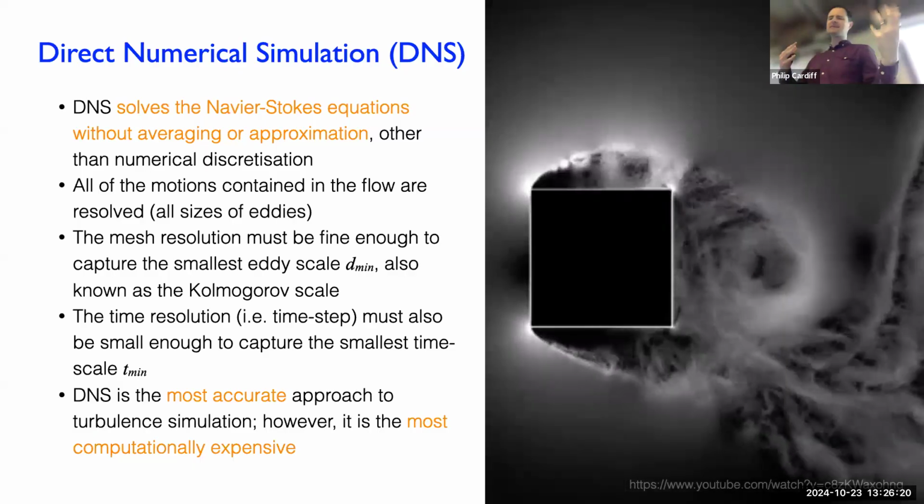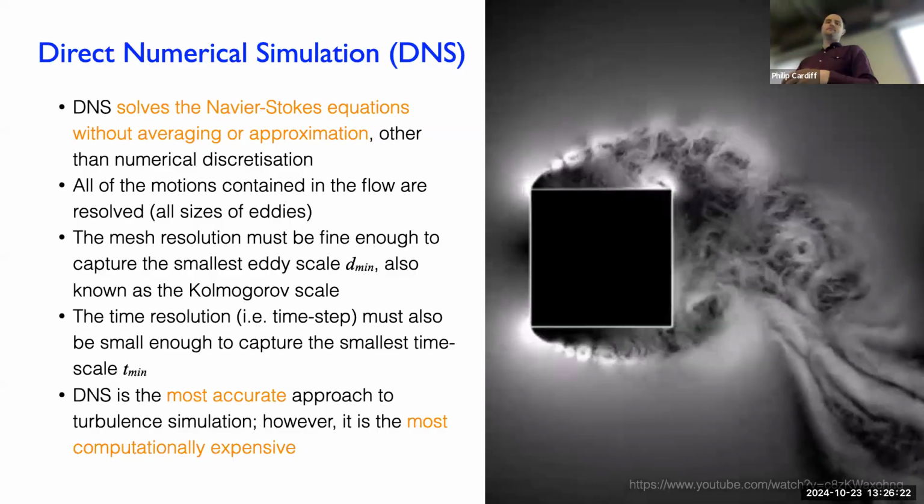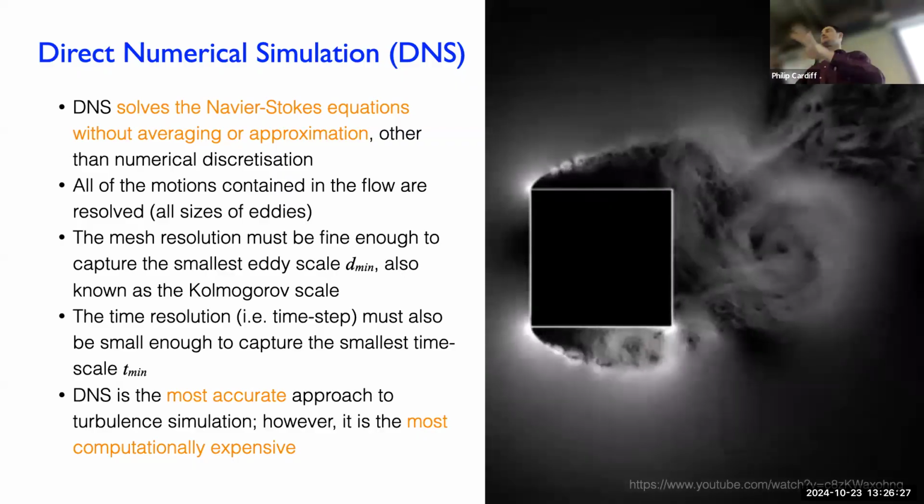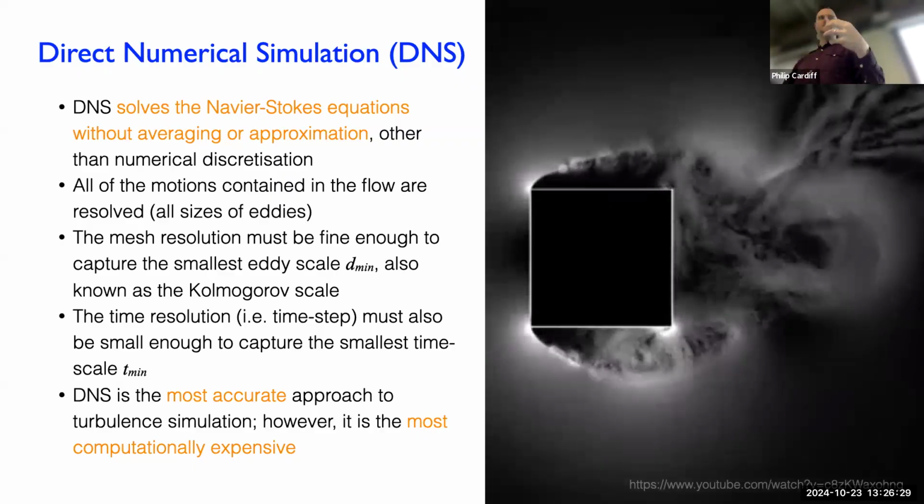Sometimes there are misleading quotes about turbulence, where people say turbulence is not mathematically understood. There are lots of things at a high level that may be difficult to predict, but the actual mathematical equations, the Navier-Stokes equations, fully describe turbulence deterministically. They're very sensitive to initial conditions. But if we calculate the Kolmogorov scales, and make our mesh fine enough and our time step fine enough, it will describe all of that. There are some practical concerns, you'll have billions of cells, etc., but that will work.